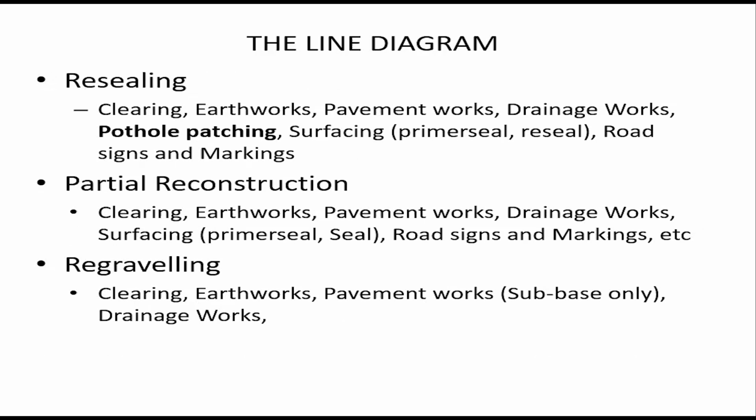And then you do surfacing work, which is primer seal and then reseal. And then do your road sign and marking. Somebody will ask, resealing, but there is primer seal in there. Yes. Sometimes some sections might be so bad, the potholes might be interconnected, so there's no need to patch the potholes. So you rather clarify that section. And that is where the primer seal comes in. Then after that, you do your classical resealing, and then you do the road line marking.